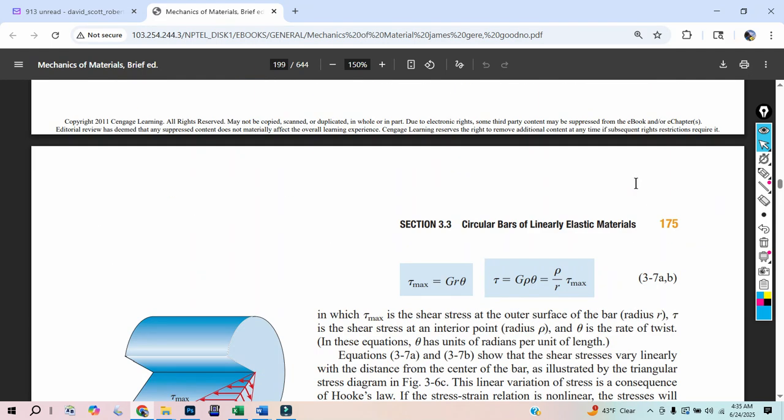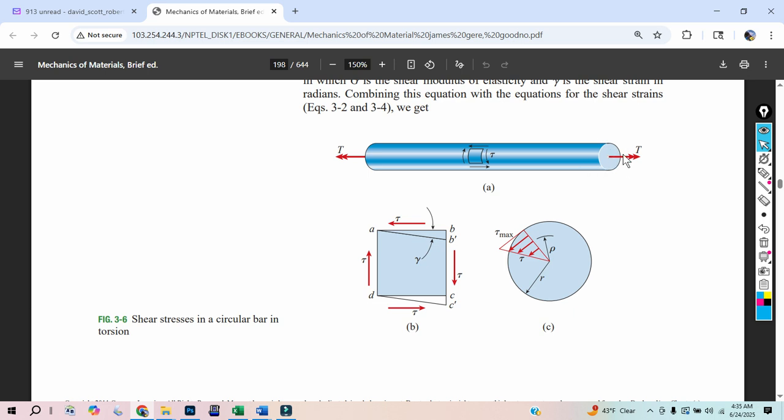But yes, if you have a wooden dowel and you're tweaking on it, it might rip longitudinally because those soda straw-like structures of wood are sliding past one another, whereas it's actually strong to try to shear it in the perpendicular direction. Longitudinally, it can just split because they slide past each other, because wood has those rings, and they make vertical, yeah.